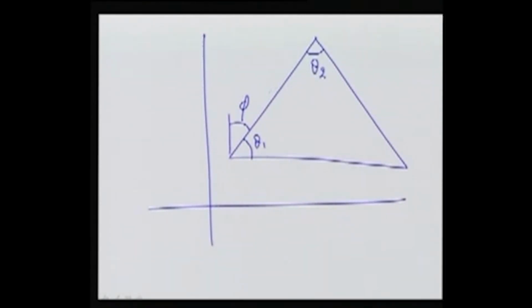I observe the length L1. What we have done so far is fixed the size of the triangle and the orientation of the triangle, but still the location of the triangle is not fixed. To fix the location, we also observe x1 and y1. So these are again 6: x1, y1, theta 1, theta 2, phi and L1. Again n naught is equal to 6.